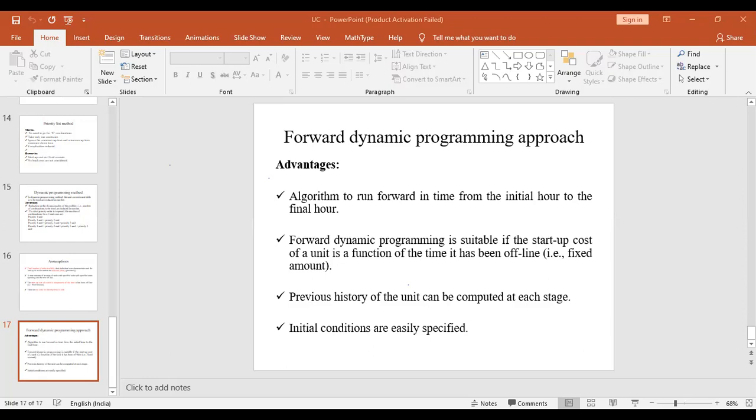Coming to another question, we are going to calculate the incremental cost for a system operating with two generating units, with power P1 and P2 in megawatts. We have the characteristic equations dC1/dP1 equal to 0.2 P1 plus 50, and dC2/dP2 equal to 0.2 P2 plus 40.